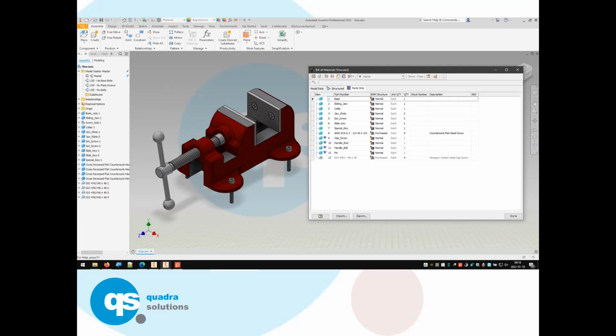Your overlay view on a drawing, yes, where you can have two positional representations on top of each other, one of them drawn in dotted, so you can see the minimum and the maximum extension of something. That doesn't work as a model state, but does work as a positional representation.